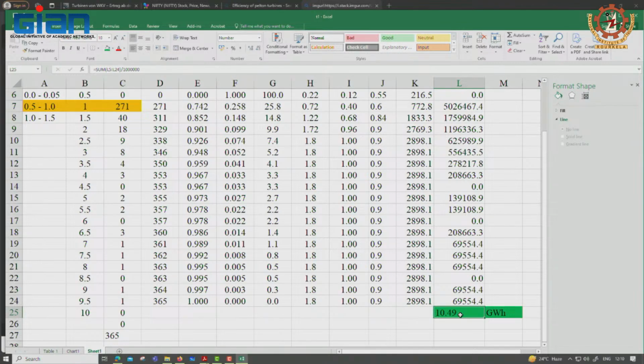So if you go for Francis, your annual energy generation will be lower and therefore your annual income will be lower. But if the total package price that the manufacturer gives you for the Francis is considerably lower than Pelton, then you can still consider it. That all depends upon your cash flow calculation, the economic evaluation.